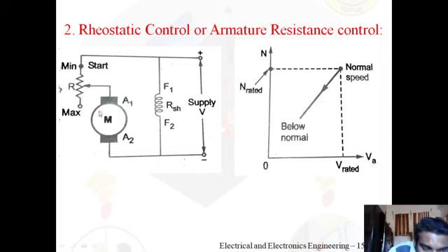So whatever voltage comes across the armature has to be varied in order to vary the speed. Let us see that. Coming to the graph, as usual on the y-axis we have taken the speed, and on the x-axis the voltage, that is the rated voltage. This is the voltage applied to the armature, the supply voltage. Whatever voltage we have applied, you can consider that the V rated.